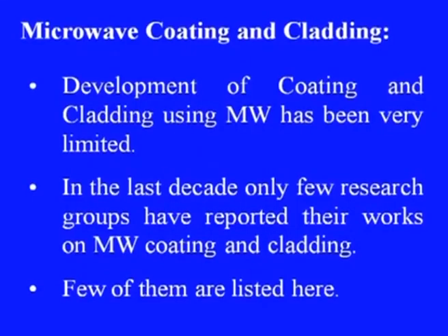As we know, porosity is nothing but pockets of defects, but in these cases the porosity is close to 1% only or less than 1%. Whereas in case of TIG welding etc., we have seen porosity can be 4%, 3%, 5% and so on, and the higher the porosity, we should say the more inferior is the joint. We have found the microwave joining to be very good.